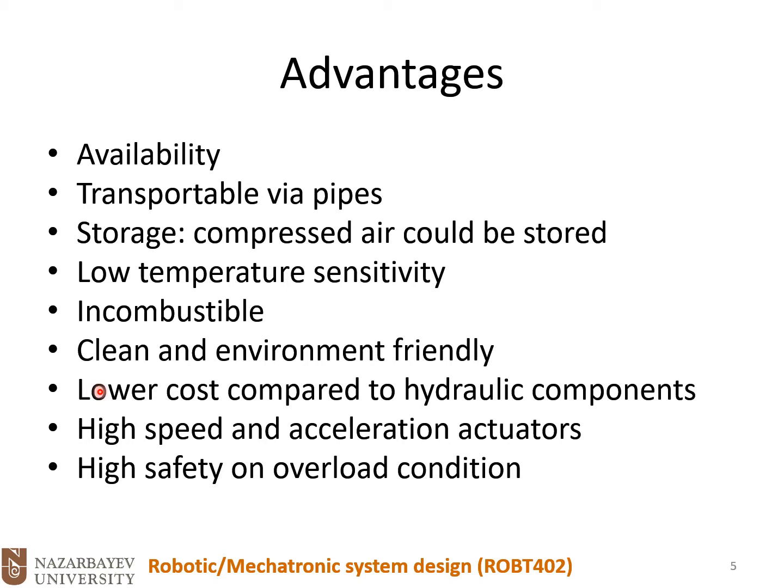That's why in pneumatic systems, we could use smaller size valves, smaller size actuators, and weaker pipes. Plus, we don't need oil, which is essential in a hydraulic system, where we must have an oil or a liquid. But here, air is available everywhere and is free.